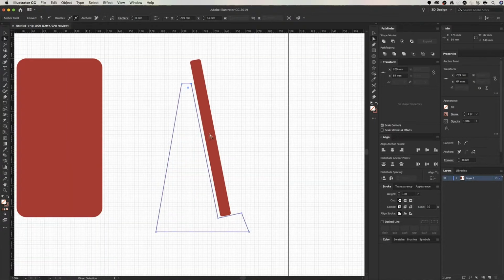So now we've got this nice angle here. We've got this nice part of the base here. We know it's going to sit in a way that I like it. Now this thing, if we just extruded this out, this would be a big waste of plastic, or we could have no infill or something like that. But let's finesse it a little bit. Let's give this a little bit of a thickness, so it's more of an outline. But before we do that, let's give this some nice fillets or curves using these smart corners. So I can bring this one down to sort of a full semicircle.